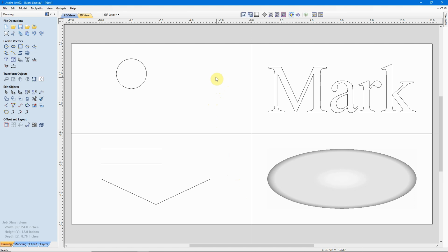Everywhere the tip of my cursor arrow goes, that's what that readout is following. So over here you can see to the right of my X0, I'm in negative X. Above my Y0, I'm in positive Y. Negative X, negative Y. Positive X, negative Y. Positive X, positive Y. It's using visual cues like those and the ones built into the various drawing tools that will help you get that location right the first time.